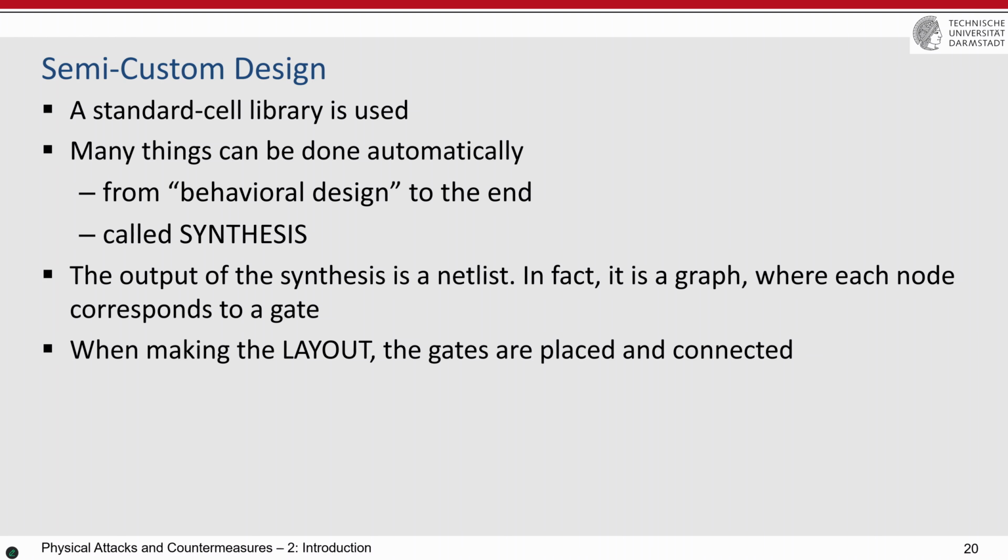When making the layout, when we want to build a chip, an ASIC, not the FPGA. FPGA is similar to this, but the components of the FPGA are different from the ASIC. This library that you have, which builds the AND gate and so on, is different in the FPGA. They are fixed components in the FPGA, and there is also a tool which says where any of these components should be placed. Because inside the FPGA the structure is fixed, you just configure it. Suppose there are some gates that you can change from an AND gate to an OR gate, or an OR gate to a NAND gate and so on, and then the connections between them can also be configured.